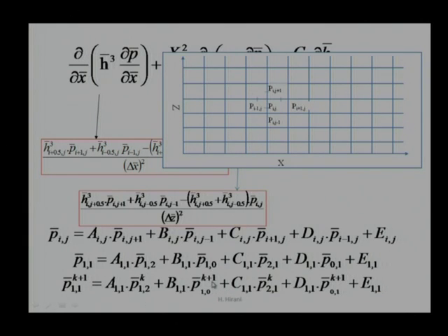That is why here we are writing the k plus 1 iteration. So, whatever pressure is already known, we can directly utilize. While coming to this term, here again p21 will not be known beforehand for our k plus 1 iteration. So, we take a value which was available from the previous iteration. And coming to the next term, d11 and p01, here again that node is already over, we already passed it, we are advancing. So, the value of this pressure will be known to us. So, it will be k plus 1, that is the recent iteration. That means two terms are coming from the previous iteration and two terms are coming from the present iteration.